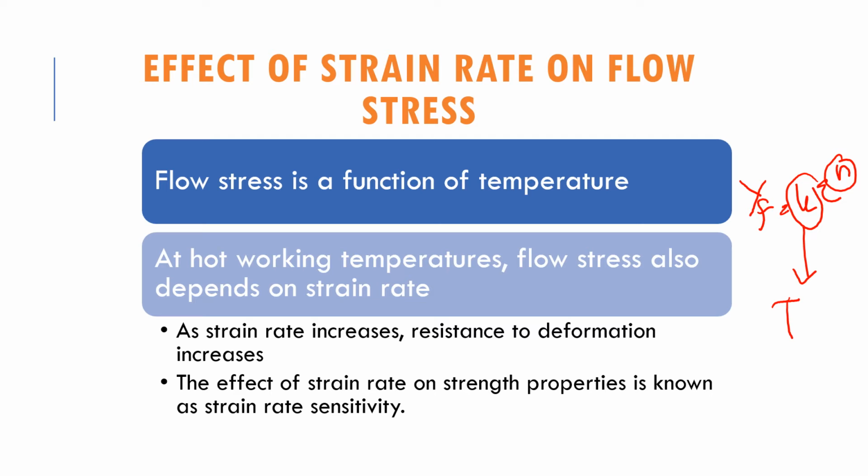At hot working temperature, flow stress also will depend on the strain rate, not only K and n, because when temperature is increased, strain rate also will start to increase. As strain rate increases, resistance to deformation also increases. This effect of strain rate on flow properties, we call strain rate sensitivity.